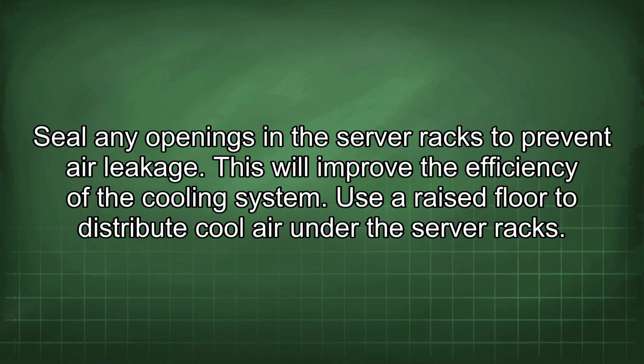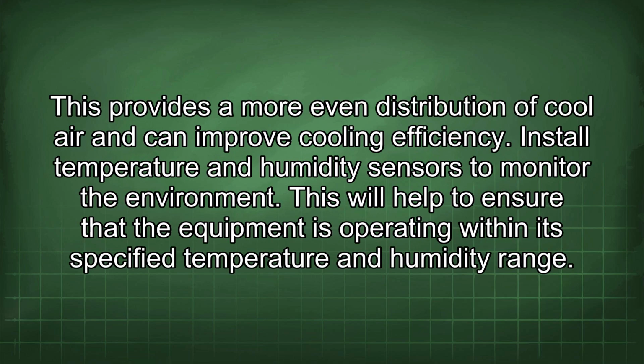Use a raised floor to distribute cool air under the server racks. This provides a more even distribution of cool air and can improve cooling efficiency. Install temperature and humidity sensors to monitor the environment. This will help to ensure that the equipment is operating within its specified temperature and humidity range.